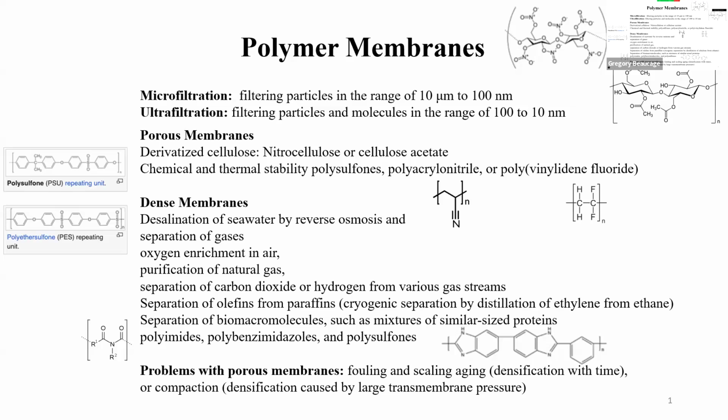There's a slight difference in size, I guess, and there's a difference in polarizability. So you can select those. It's like a membrane that does that. So people are working on developing techniques to separate various gas streams. I mean, air is mostly nitrogen, and you want oxygen from it. But oxygen is more polar than nitrogen, so you could make a membrane that separates oxygen. It's like 21% oxygen and the rest is nitrogen, basically, and some other things. Right? So CO2, but basically not much.